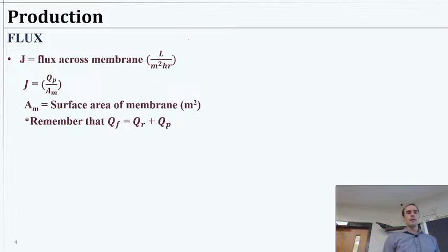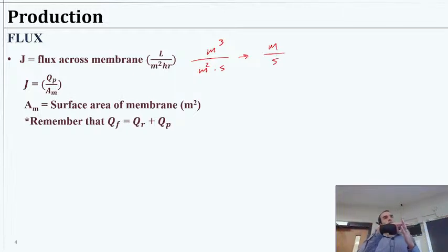So really what it is, whatever units we use could be cubic meters per square meter per second, could be liters per square meter per hour. Whatever it is, it ultimately can come down to a speed at which water is traveling through some porous surface, right? So we'll describe flux as J, and say J is going to be, as a rule, the flow rate per area, right? So we always know if we have the area and a flow rate, we can solve for flux.